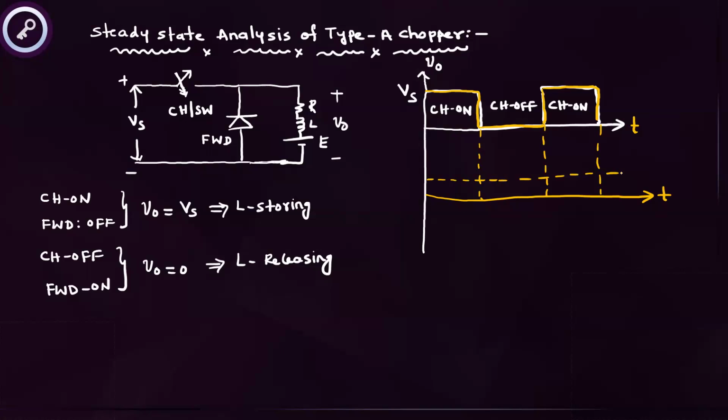That is a continuous mode. The current is changing from I minimum to I maximum. This waveform applies to the buck regulator and the boost regulator also. Again the current changes from maximum to minimum, again minimum to maximum. Then this is the average current.